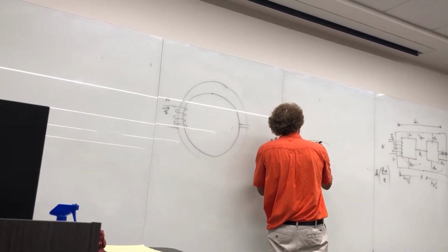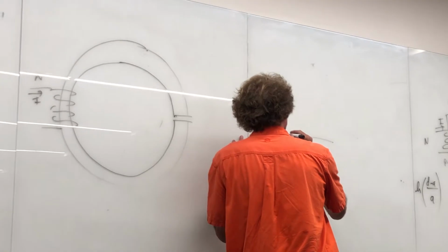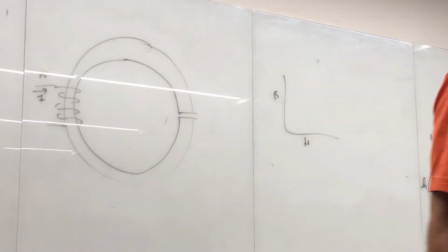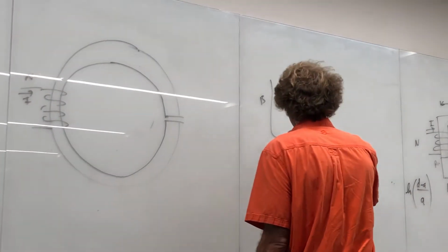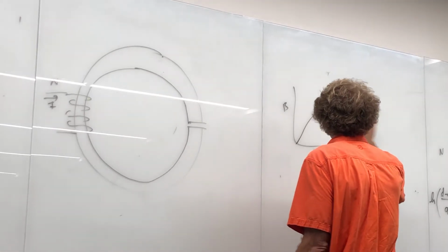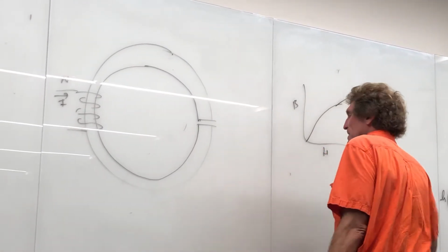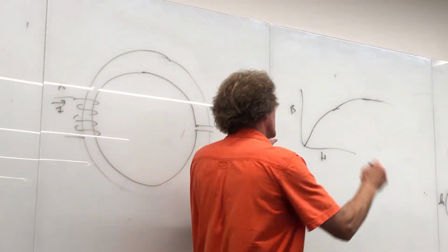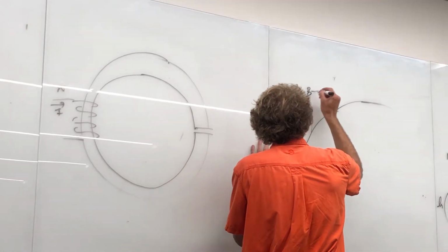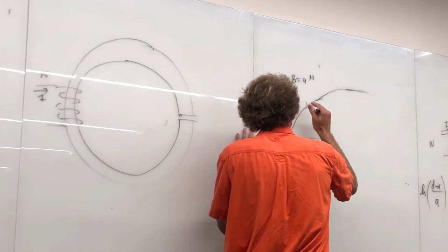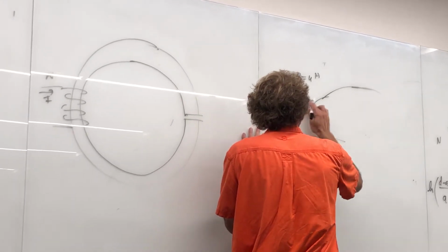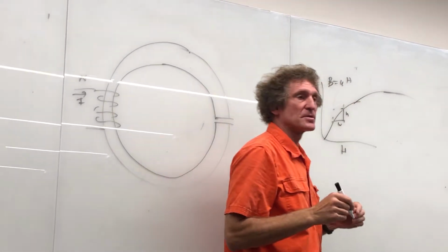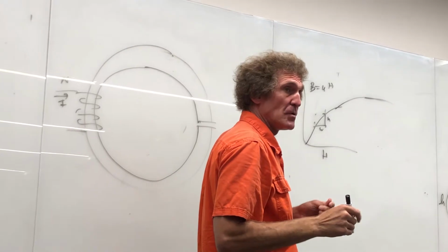So is H down here and B here? Yes, sir. It's a weird curve. Let me tell you about these problems. These are typical things that you get in power and stuff. They're for transformers, BH curves. There's a linear region down here. You see how it's about a straight line? Down here, B can be equal to mu H, and mu is simply the slope of this line, whatever the height to width right here would be as a slope. And that's how you get mu, by estimating.